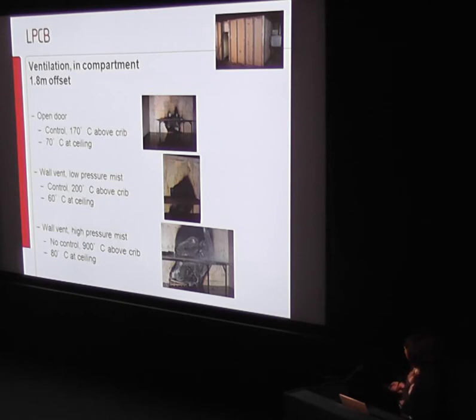So it was a challenging situation, and I would say with ventilation in the small compartment, we got control and reduced temperatures at the ceiling. We carried this out with a low pressure system, but we also used a high pressure system where you've got much smaller droplets. In this case, I would contest that we didn't have control, and we had very little suppression. We had flames, where it's gone grey, all the plywood's burnt away, so there's nothing left to burn. We had flames continuing throughout the period of water spraying.